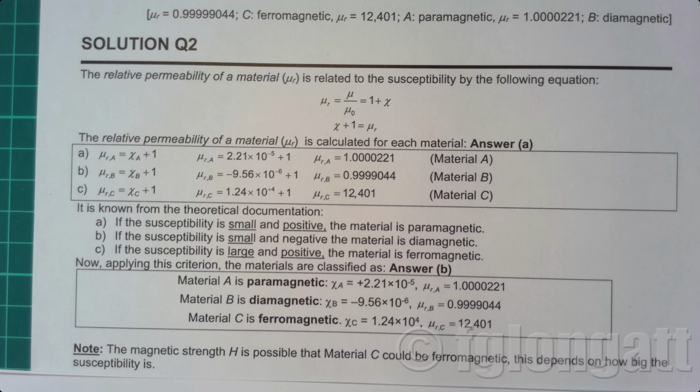I believe that all of you can now see that the magnetic susceptibility and also the permeabilities are very important properties defining the magnetization of any material. So it's very important when we are selecting the final material that we need to use for electrical machines. Using ferromagnetic material will allow me to reduce the losses in the magnetic core, so the electrical machine will have lower losses.